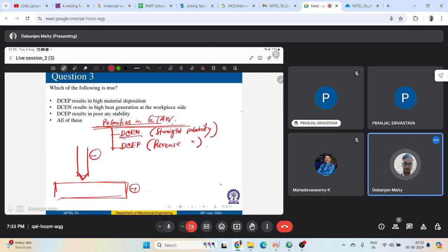So electrons are emitted from the tungsten electrode, if it is gas tungsten arc welding, and accelerated while traveling through the arc, as I was saying in your arc physics, right? So a significant amount of energy, called the work function, or I was calling it the thermionic work function, is always required for an electron to be emitted from the electrode.